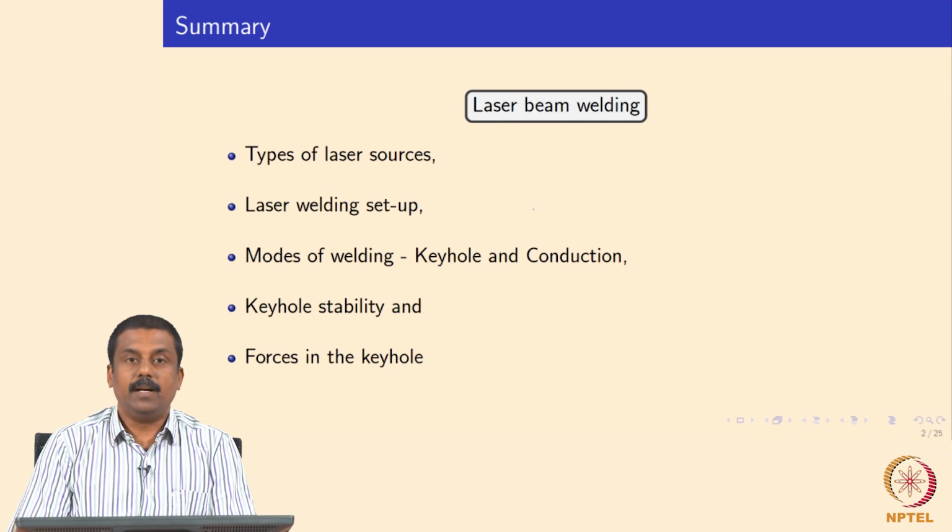So in order to improve the transfer characteristic to our benefit, as well as to reduce the heat input, we modified GMAW, gas metal arc welding. These modified GMAWs are sometimes used in the automotive industry to weld thicker sections, for example advanced high strength steels, or in some applications where the weld strength is not really significant. So we may also use the GMAW processes to do brazing.